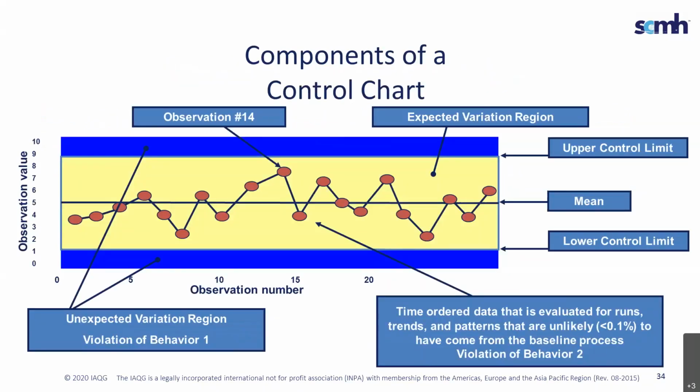All right, so here's an example overview of what you see on a control chart. Typically, you'll have plus or minus 3 standard deviations as your control limits. Anything above and below that is a violation of control limits. You have the numbers in time order. I've seen a common failure mode where people order them not in time order, but from high to low or low to high for whatever reason. So you get this weird trend line down. Obviously, that will flag immediately as a control violation of a special cause.